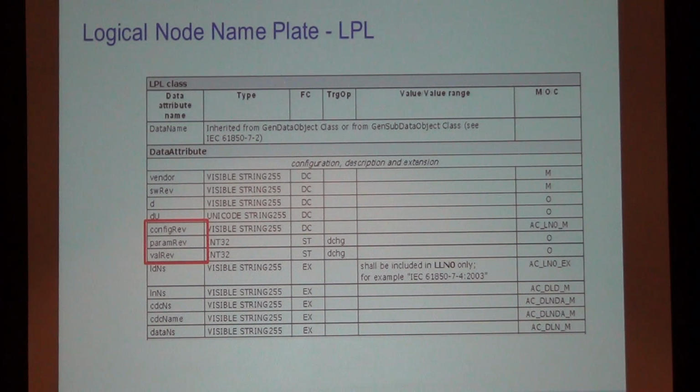That tells you that there's some new object that has been deleted or added to that device. In other words, the semantic characteristics of the device have changed. And so you have to be careful of that. If you're a client, you want to refresh your object list from the device to get the latest version of how that device is configured.